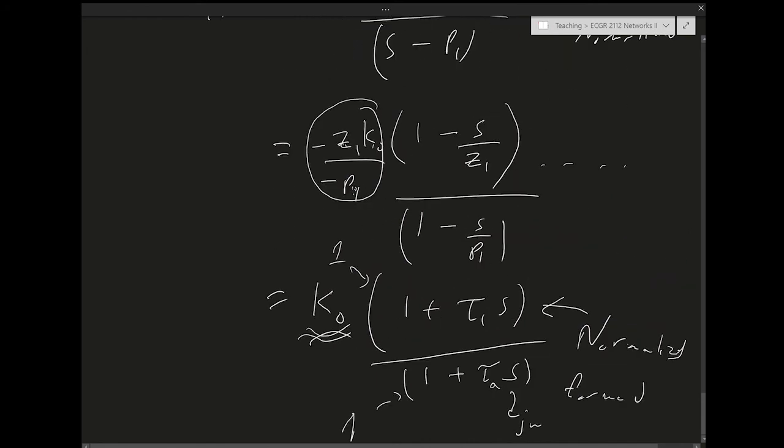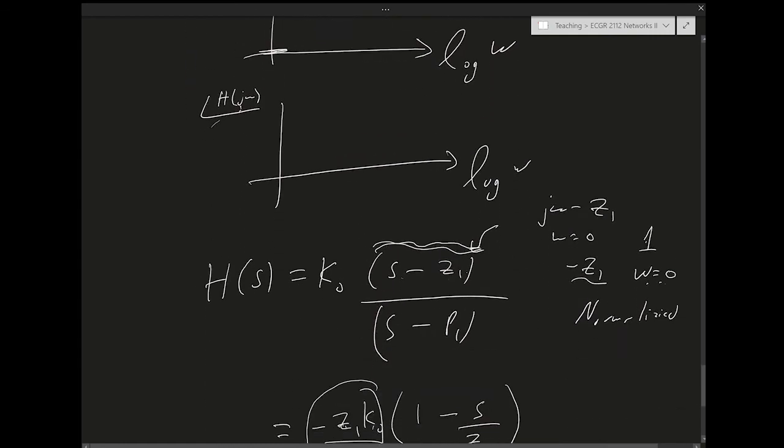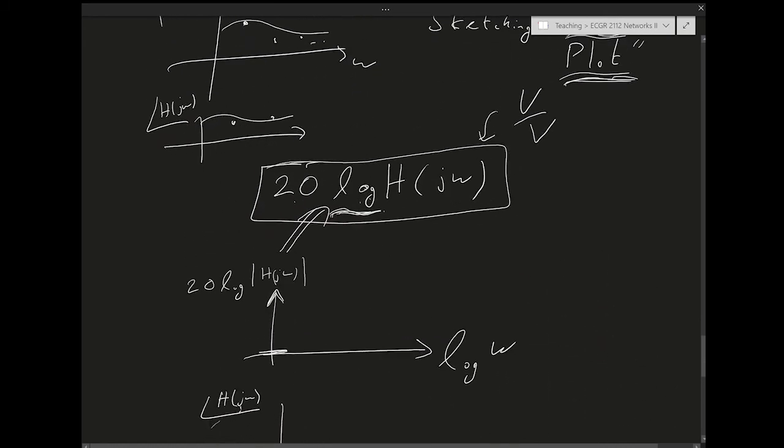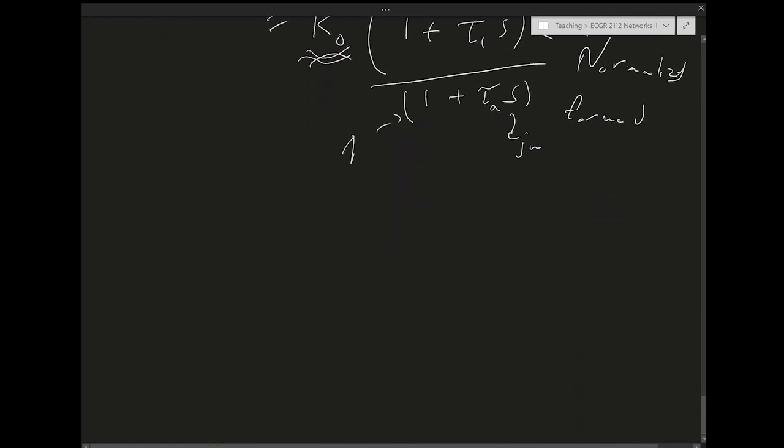So okay, those are the two bases for starting the discussion about Bode plots. We need to normalize the pole and zero representation of the transfer function, and then we are looking for the 20 log, right? So let's rewrite the transfer function in normalized manner. So H of s would be like this. It will be k0, and there's a bunch of zeros and poles, right?